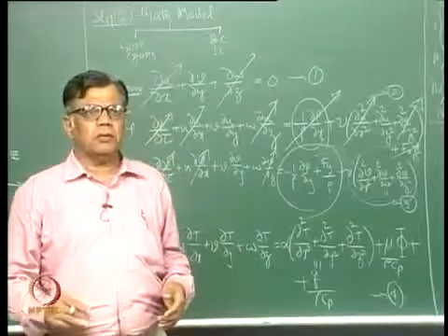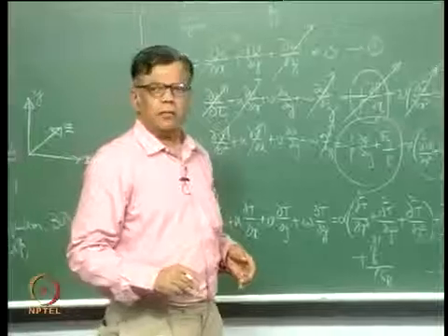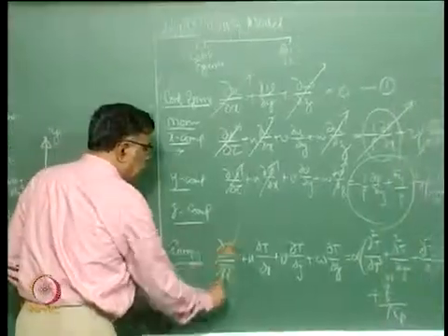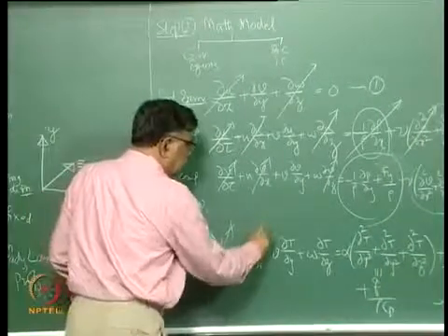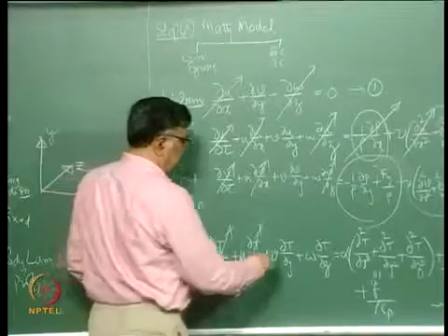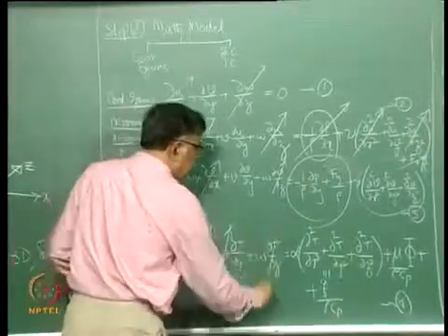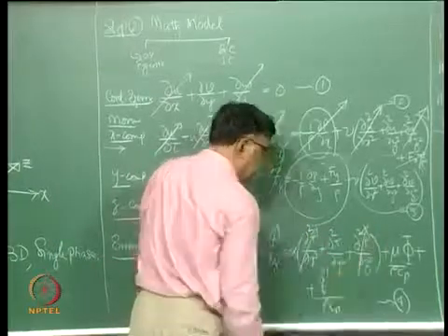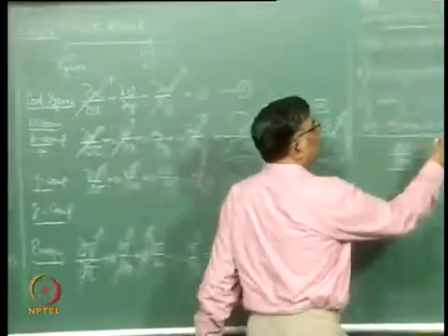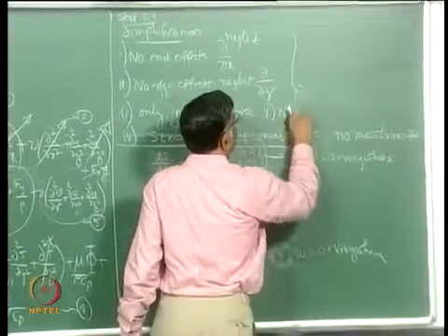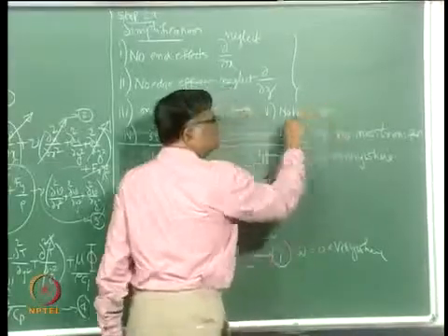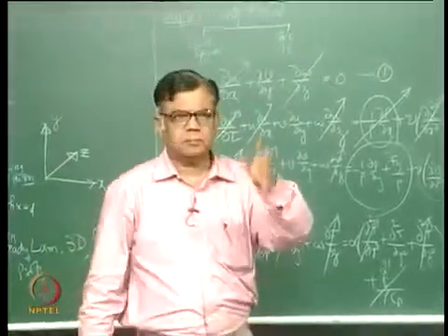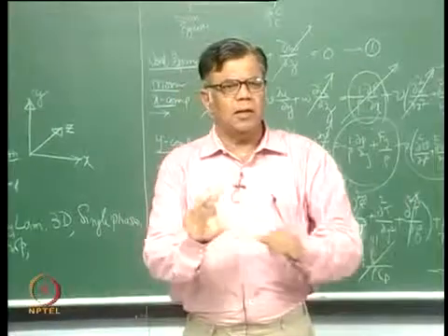Quickly do the energy equation, can you do it? It is equation 1051. I have written it down here, so we will do this. Del T by del tau is 0, del T by del x is 0, V is 0 here, del T by del z is 0, W is 0, del square T by del x square is 0, del square T by del z square is 0, and now we will put one more condition here, no internal heat generation, so that goes off. Phi is full of derivatives.